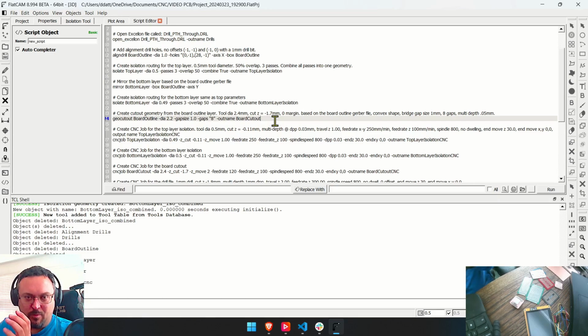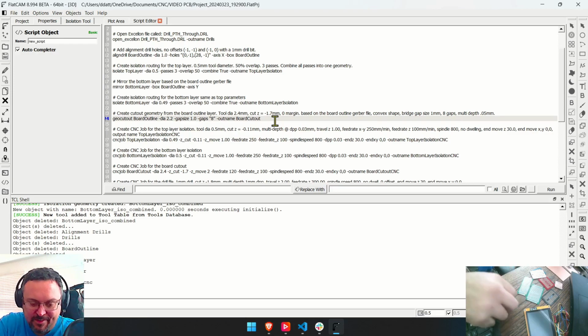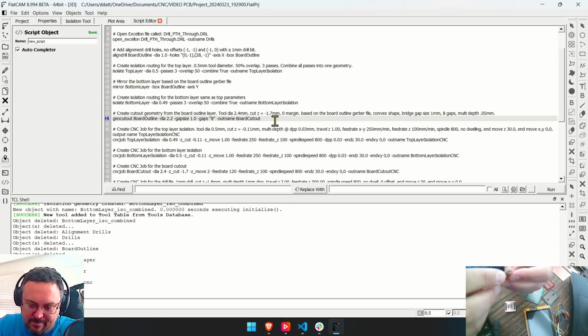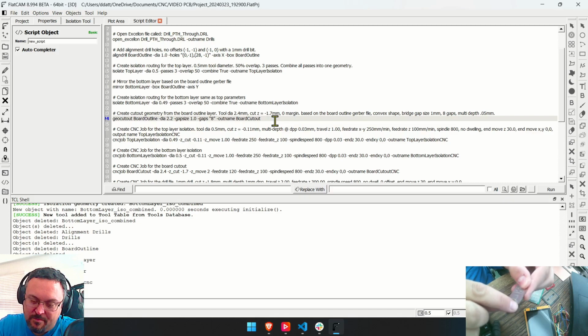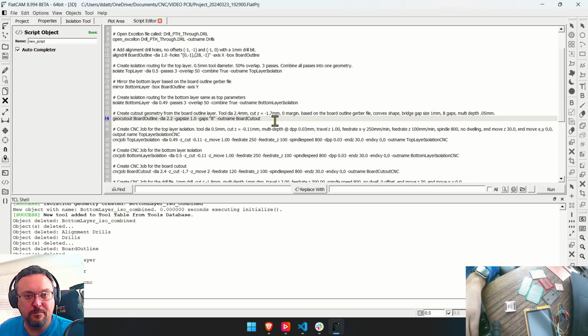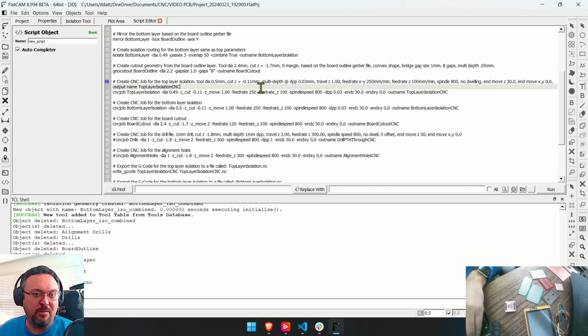So about 0.2 millimeters on each side, 0.4 millimeter total, all the way around the board is how much bigger it was. So you can sand that down, and that's okay. It's not a huge deal. And actually, I do sand it as a general rule. So maybe that's something I should keep doing, because if I did it exactly as is, some of this copper would be gone, probably, because that's probably the 0.4 millimeter. That doesn't matter. We'll use the right tool size. There's a way to add a margin if you really wanted to do that, so you should have the right tool size.